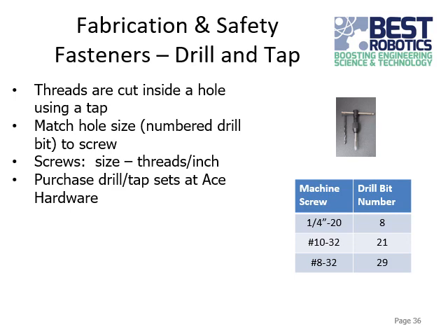Just make sure when you are tapping it, you can see it in that picture on the right, it's a little T-shaped part, a lot of times you'll need to go in a little bit and then back it back out, so that it can remove the bits of metal that are cutting out as it goes along. Otherwise, that metal can fall into the bottom of the hole, or get stuck in the cutting surfaces, and then mess up your threads. Also, sometimes it's good to use cutting fluid to keep the tap cutting surfaces sharp and all that.